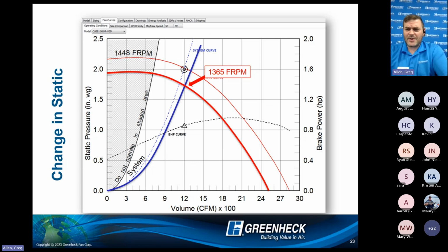I mean, usually they have about an 80% turn down. That's a huge range. Turn up, well, the amount you have to turn up goes back to your original or initial fan selection. Did you select the fan, a small guy, the most cost-effective one that's maxed out just to hit your point? Well, there is no turn up in that scenario. I have another slide here that's going to kind of hit that even a little harder.